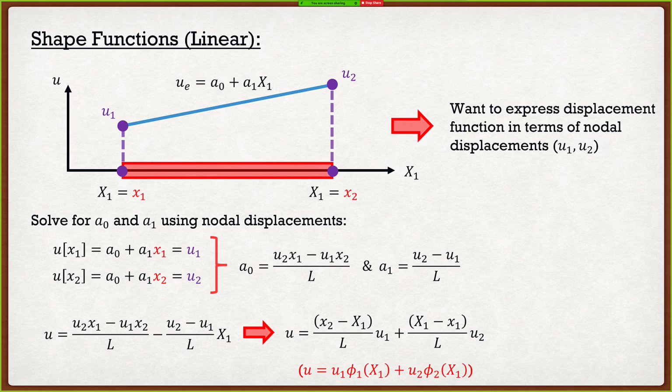One of the things I also want to emphasize, because we're going to be seeing this later, is that u1 and u2 are nodal displacements, as I mentioned. Those are just constant values, because it's the displacement at a point. It's not a displacement over a range, it's just the displacement at some points. So those are going to be our constant values, which we typically had before as a0, a1, a2, a3, etc. And in between them, we multiply them by our shape function.